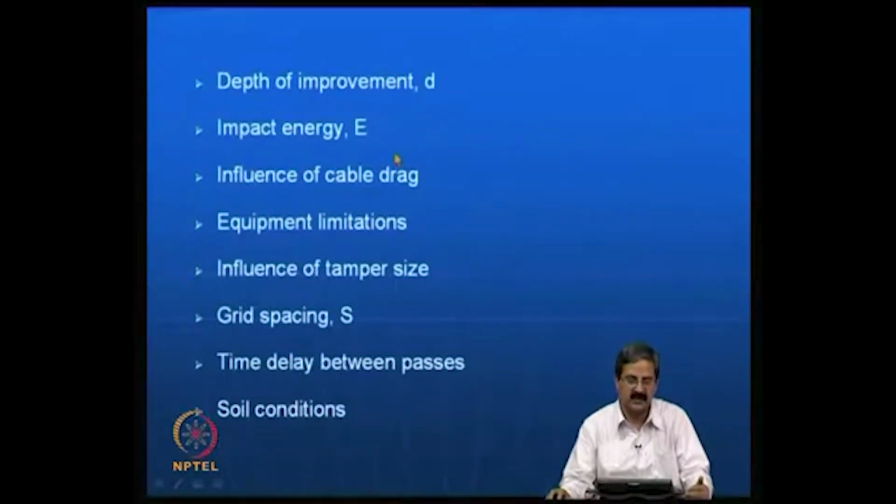So what we do in the design is that you can get the depth of improvement, you can know what type of energy you can give as an impact, then the influence of cable drag, equipment limitations, like we should understand the equipment that is there, because you are planning for some energy level and that is in fact related to the equipment.